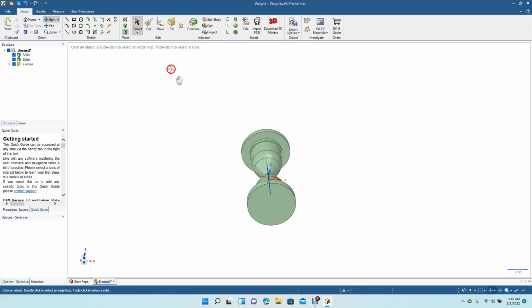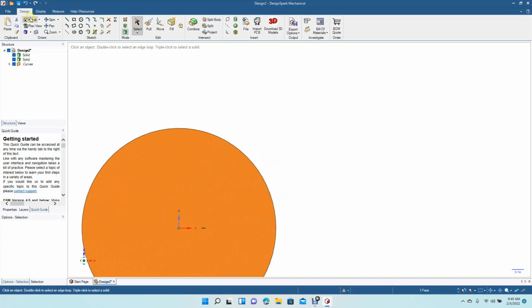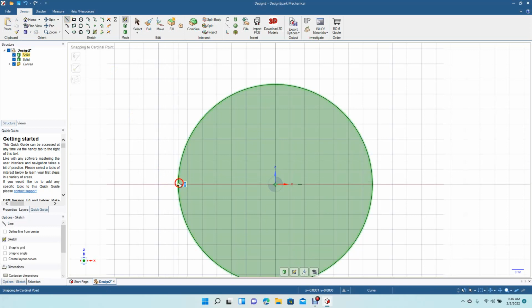All right, now we're going to put some lines in, some circles in here. So we'll go ahead and go like this. I'm going to check plan view, Control plus to zoom in 2 times. Let's pan over. Let's grab the line tool. Put a line right across like this. Grab our circle tool, 0.2, or actually let's make this 0.16.